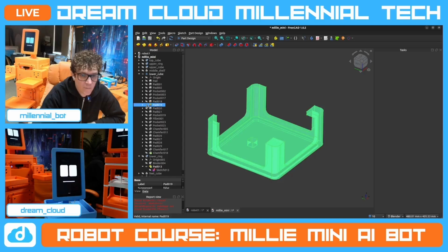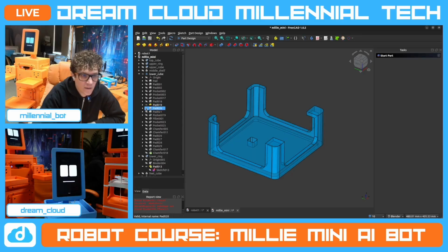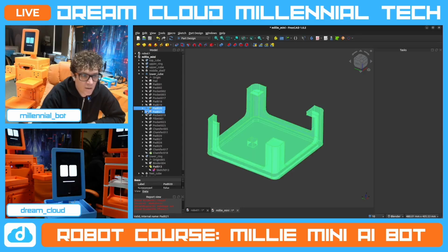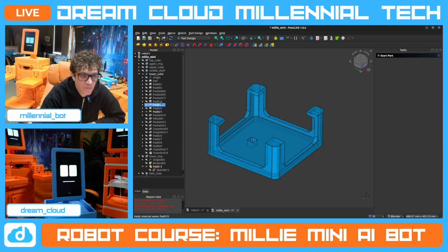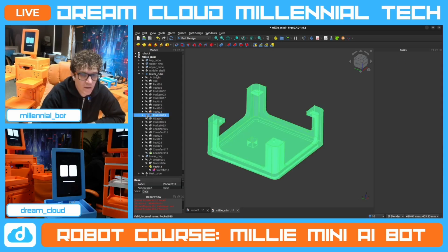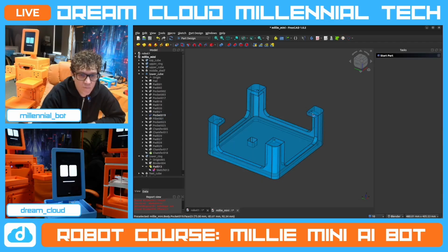Pad, this pad, right? This pad, and then this pad. So all those pads came out of right here. And basically that was just creating a little square on top and then creating a pad, extruding a drawing into a pad, right? And then we have the pocket. So this pocket is actually the four holes that were put in here, and that's where the bolt goes. And then the fillet was to round those edges, right?